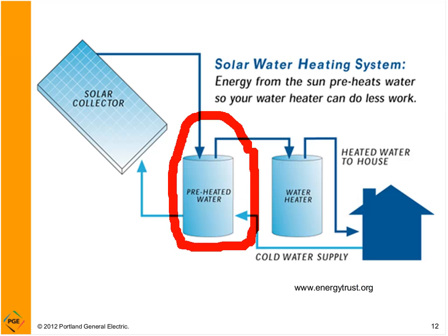Basically, the way this works is you take cold water coming in to your facility. That generally is in the 40 to 50 degree range Fahrenheit, so it's very cold. As you heat it up and put it into your facility, we're generally in the 110, 130 degree range.